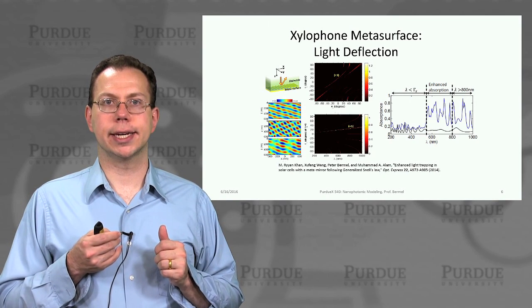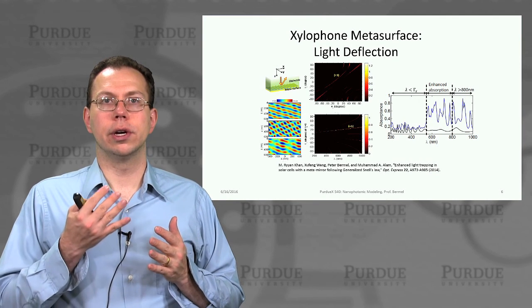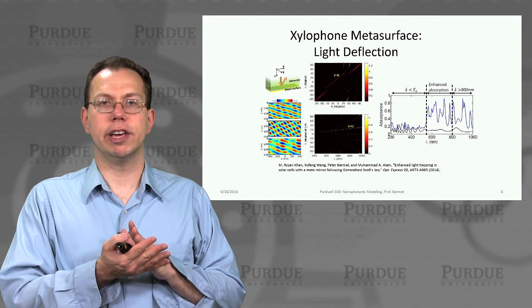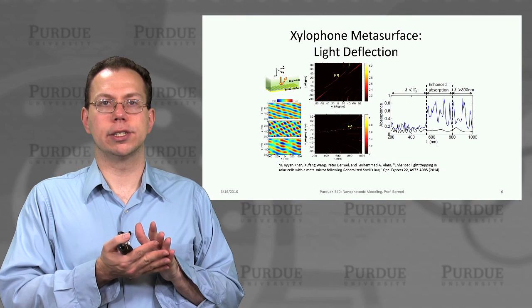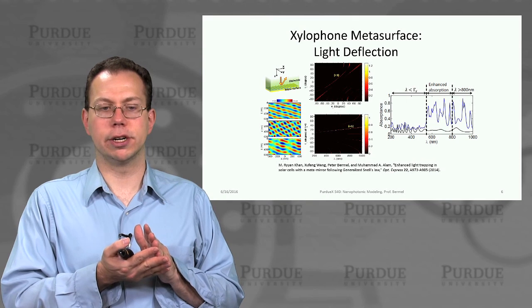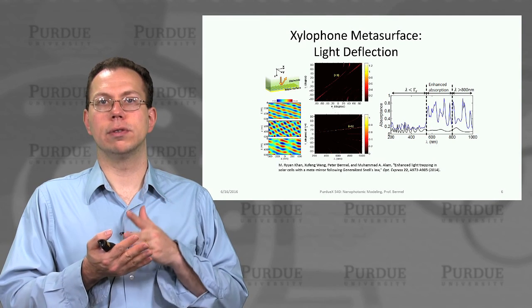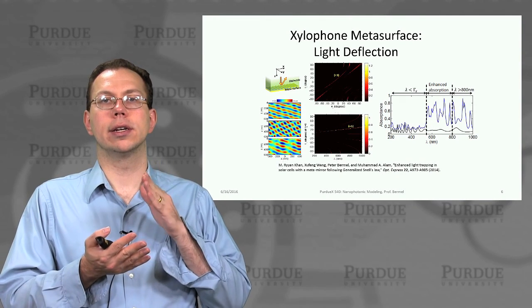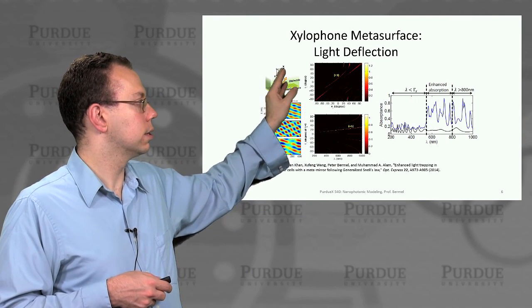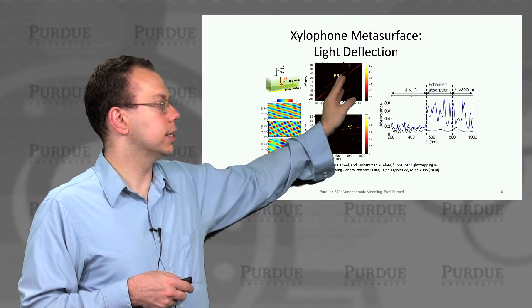For more advanced applications, we talked about metasurfaces. We said metasurfaces are a way to create light trapping in photovoltaics and photodetectors that rely on creating a phase shift on a very thin surface at the bottom of some semiconductor absorber or other absorber materials. We showed that if you design these correctly and essentially have a uniform phase front, then light coming in normal can be deflected into a much different angle. That's illustrated as this +1 mode.